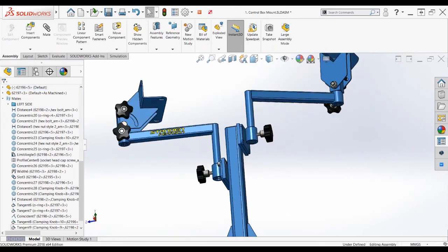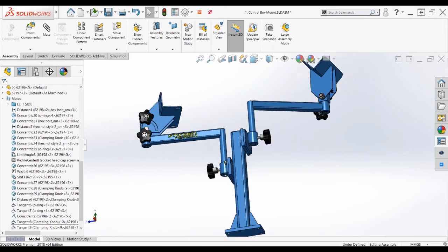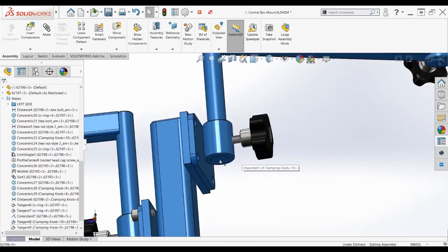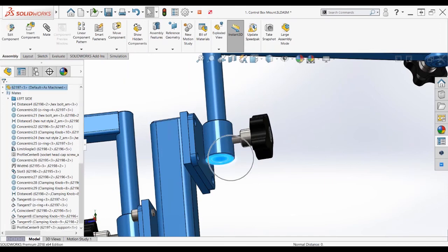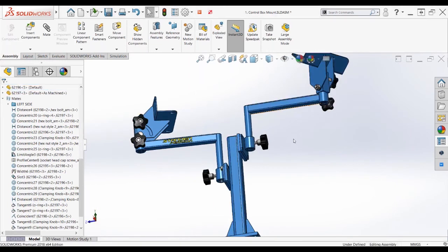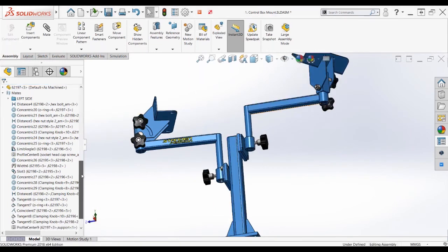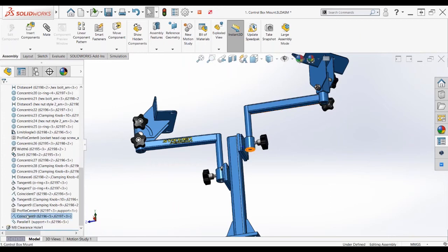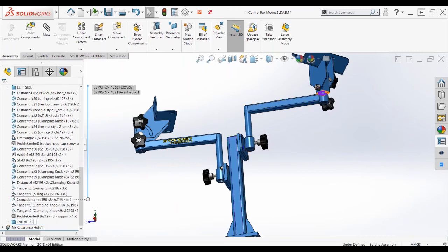But if I want to reline it up again, that's more rework for me that I don't want to do. So I'm actually going to create the mates. Just give myself a coincident mate at the bottom and a parallel mate for the arm. And what I'm going to do is grab those mates in my feature tree, and put them inside of a folder, and I'm going to call that folder my initial position.